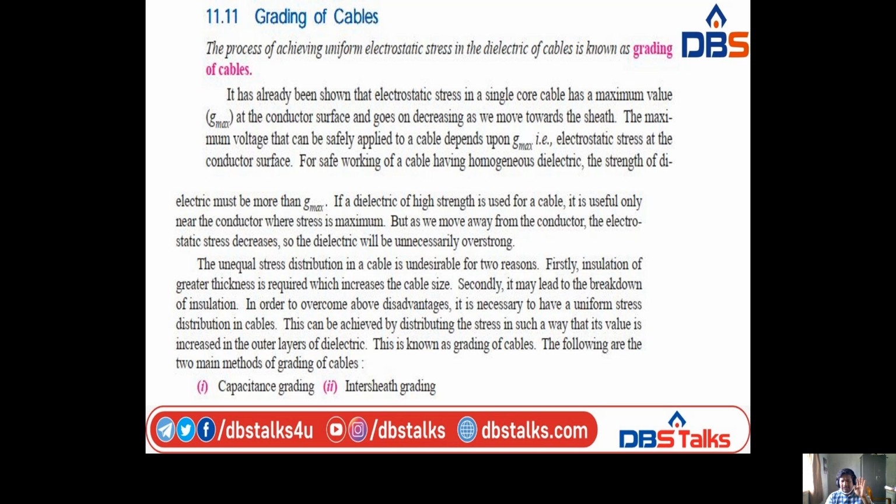There are two main methods of grading of cables. First one, capacitance grading. Second one, Inter-Sheath grading, right? So what is a grading of cable? The process of achieving uniform electric stress in the dielectric of a cable is nothing but grading of cable.